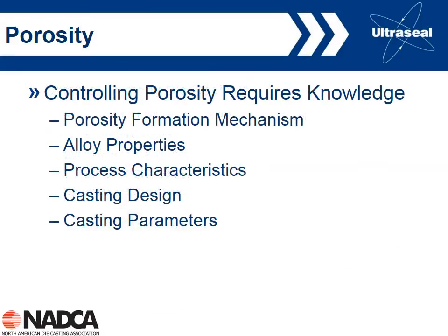So we really want to get some knowledge in terms of understanding how and why porosity forms, and that allows us to control the porosity better. In this webinar today, the first of 4, we're going to talk about the mechanism of porosity formation, to get a better feeling for why porosity is a characteristic of our die casting process. We'll talk about alloy and alloy properties and how they can affect the distribution and size of the porosity in our final product.